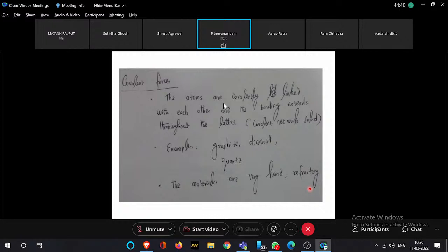Okay. All of you know furnace. Have you heard about furnace? Yes. For example, I want to heat my material at 1000 degrees Celsius. I use a furnace. So what is the fundamental principle of a furnace? Basically, it is based on Ohmic heating only. You will have a ceramic material on which a coil is wound, and then you will pass a lot of current through it, and the power dissipation will increase the temperature of the furnace. And you can control the power, so obviously you can control the temperature.